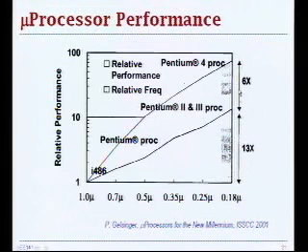Now it happens in real life that you have an additional 6x improvement in performance, and the reason is what we discussed in the introductory lecture: you have more pipeline stages. You are shrinking your logic depth between the pipeline stages, so that gives you the ability to increase the clock frequency, and also you are using more clever circuit design ideas.